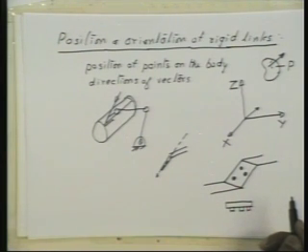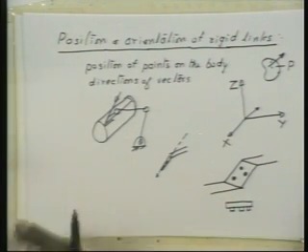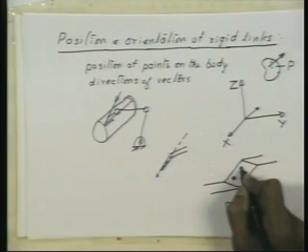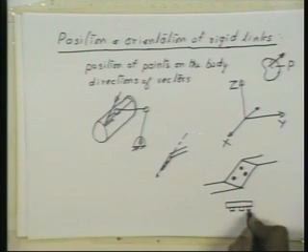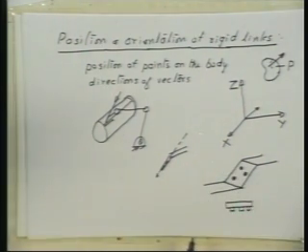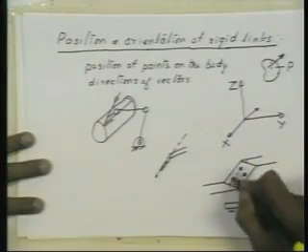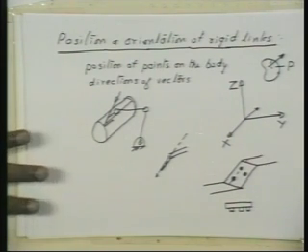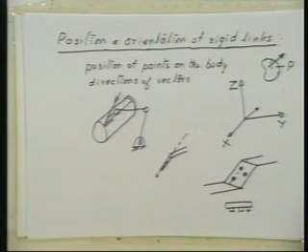One vector direction. So now you are saying 2 points. So let us take 2 points. So I take this particular point. So this center of this particular peg will have to be poised on top of that hole. Correct? Is it sufficient? Not sufficient? Right, because once you position these 2 points in space like this, I can rotate the whole body about this line, right? So we need to figure this out properly, right?